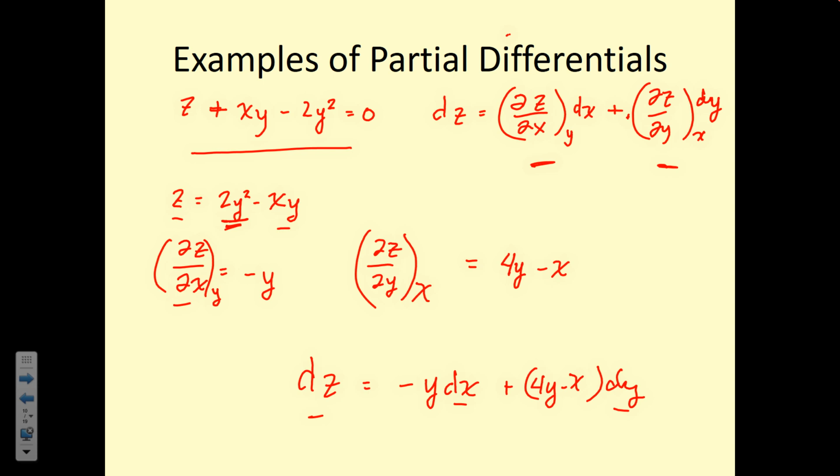Entropy? Entropy, yeah. So this is a way for us to look at how changes in other property values are going to affect some other property value. And because we're using partial differentials and we're assuming that it's linear over an interval, it's not going to be exact. But in some cases, that's the only way that we can calculate property values, like entropy, without having to measure at every single little interval along the way.